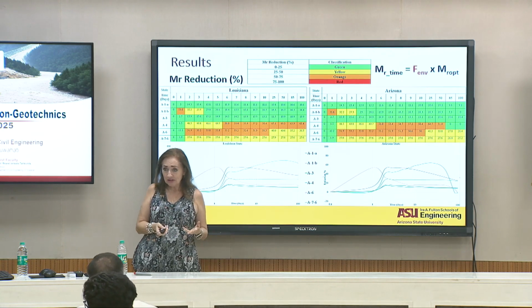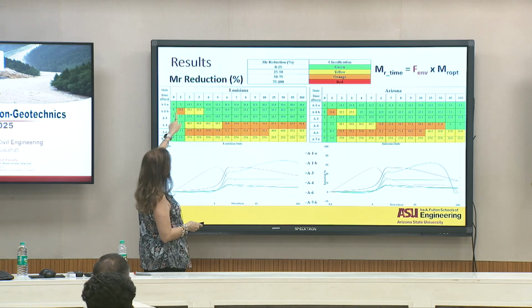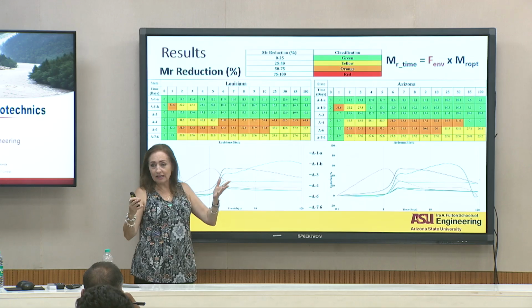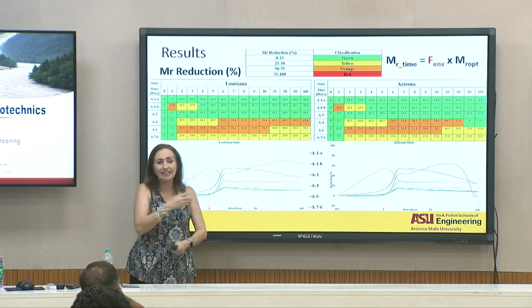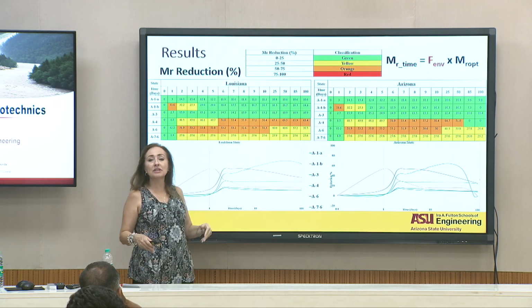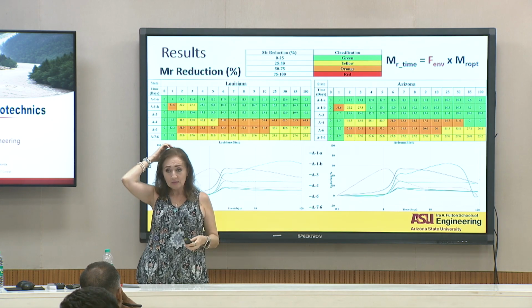For the opening time, for the recovery time, you're going to tell them, look at this. This one goes to 53%. I'm very sure by the 5th day, you lost only 20%. So probably you're going to be able to start getting the small trucks or something like that. If you have a low volume road, probably that's not going to be a nice thing to do. But if you have a high volume road where they're looking at the number of big trucks, probably they're going to be able to get cars around that with a 20% reduction with no problem. So this is something that, in their experience, they will know where to open the road. But basically, we give them a tool.